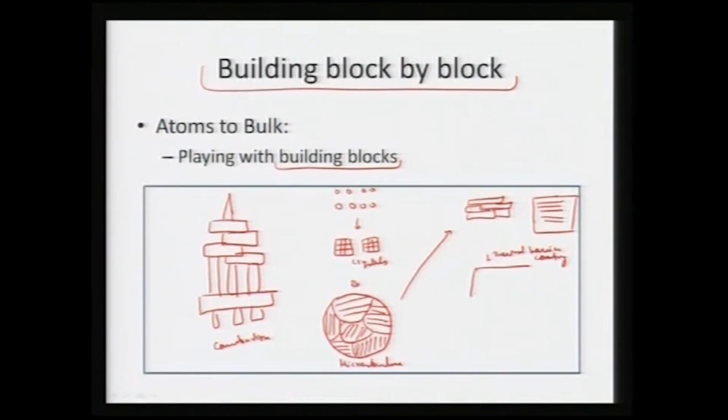One material that can sustain very high temperature is nothing but ceramic. So, we can have a ceramic layer, then we have a bond layer, and this is the base material which is now taking the maximum load. This is nothing but a metallic base material, it can be a super alloy. So, we can see that this structure can take much more load even at high temperatures, because now we have a barrier of thermal coating.